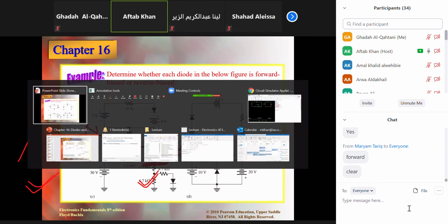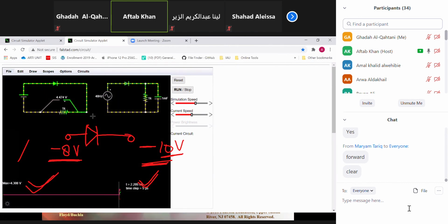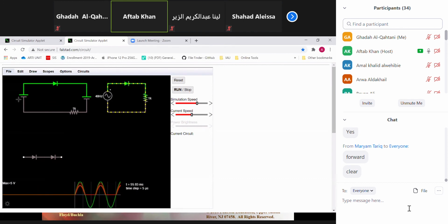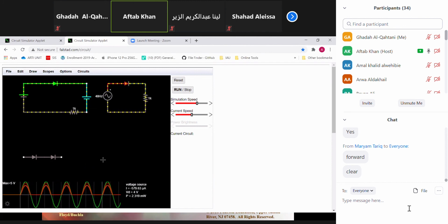It's so simple. As I give you an idea here, you can just draw some circles, 2 batteries here, and then you can understand that one also. So here are 2 batteries. When we run this, you can see no current is flowing. Why? Because it is 5 volt. When I make it 4 volt, see, it is working now. You can see easily, the diode is in forward bias, right?